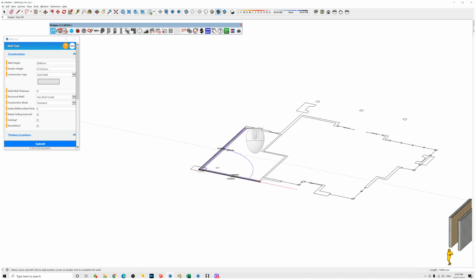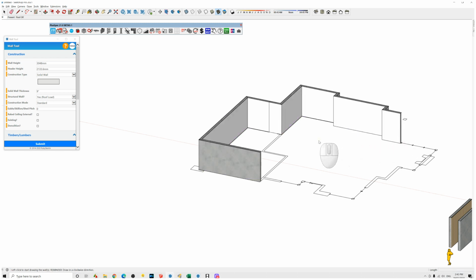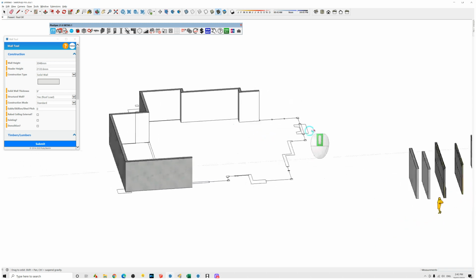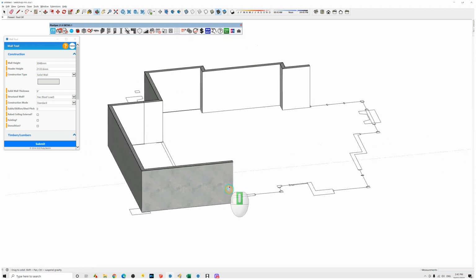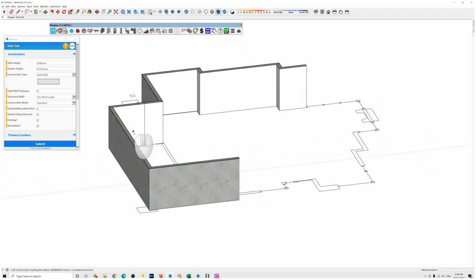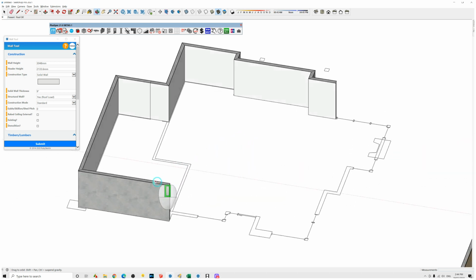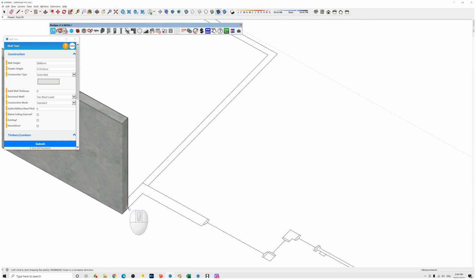I quickly took an overlay of what he was doing there, and I'll draw a little bit of it. From this, I can explain what you need to know when you're using 3D BIM software. I drew from the outside of the wall, but I could have drawn from the inside. It wouldn't matter. Once I start to detail this up and add thickness, materials, and products to this wall, it has to change in thickness overall somewhere.